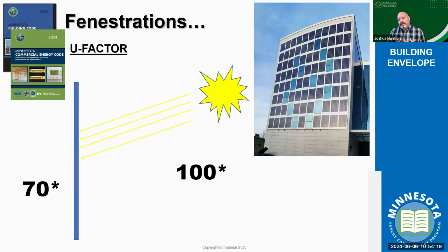Remember, solar heat gain generally affects the heat coming in. U factor will affect the heat going out, although U factor affects both. A better U factor will resist heat transfer, or controlled conditioning leaving that system.